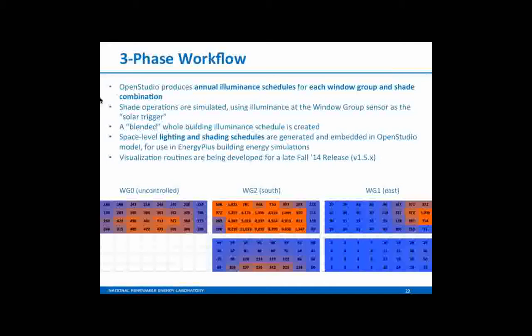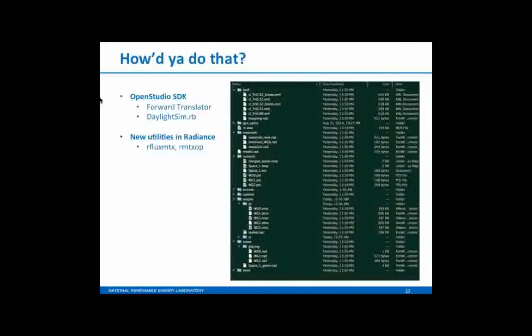And the beauty of this is that you can mix and match. So the reality is if you had some sort of control on this blind system, you'd probably take the results from this window scenario with the blinds down because there's all this direct sun coming in, there's glare, there's overheating going on. But over here, maybe the user could tolerate just the sky brightness. So you'd probably take this answer and this answer plus this answer and merge them all together. And this is what we can do in OpenStudio now. Play this game of mixing and matching to give you a result.